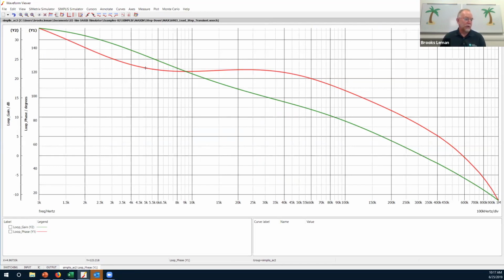Either you have to manually run long time domain simulations over and over with different stimuli, then stitch the results together manually, or create and correlate a second model, an averaged linearized frequency domain version of the time domain model. So to get Bode plots in SPICE really takes a lot more time.